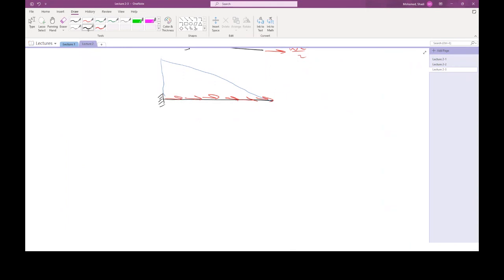So in this case, you have a very small element right at the point where you need to have the exact value for the stress. And then the other one can be very big. I mean, this is called the graded finite element. So whereas you have a stress concentration, for example, if you have a reentrant corner, you're trying to solve, let me just try to be more neat in my drawing, sorry.